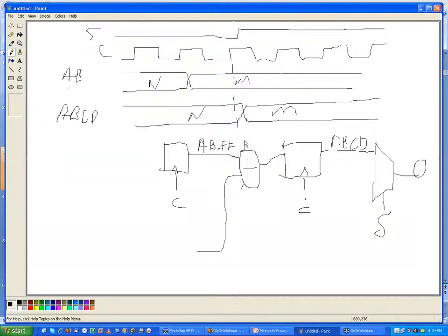No, this is the output of the first flip-flop and the input of the second. One's transferring, the other one is looking at the output of that AND gate in the middle, which I assume is very fast relative to the clock. Oh, okay. You're talking about this path right here. Yeah, I'm thinking that the output of the second flip-flop is maybe... You don't know whether it's got the stuff from the same clock cycle at the input flip-flops propagating all the way through at the same time, or if it takes another clock cycle for it to get there.